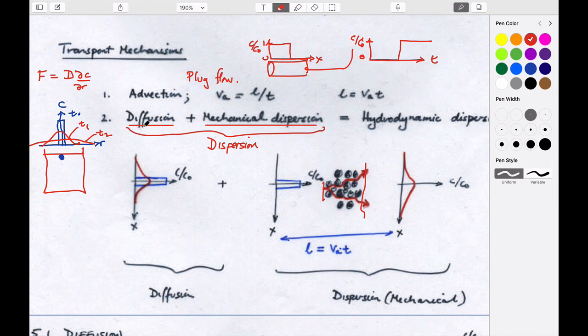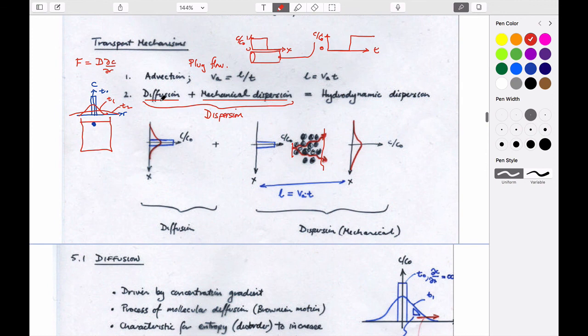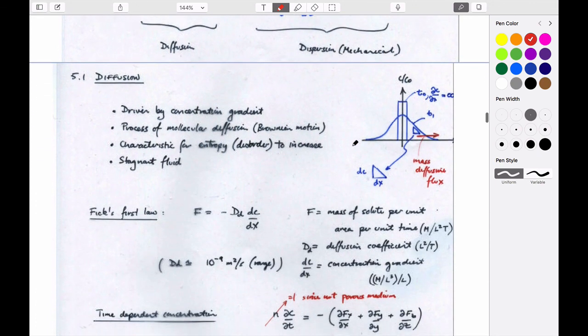So when we look at transport mechanisms of dispersion, we include both of these two terms together. But we deal with them slightly differently when we deal with them, okay? And so that's what we'll attempt to do. So what we'll do is we'll talk about diffusion first, we'll talk about dispersion second, and we'll talk about advection as the mechanism to do it. So how they're combined is that this is chemically based, this is mechanically mixing based, and this relates to the physical translation of the beaker across the room as it goes from this location here to this location downstream.